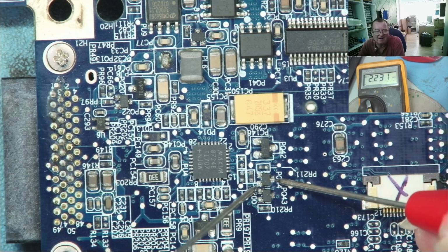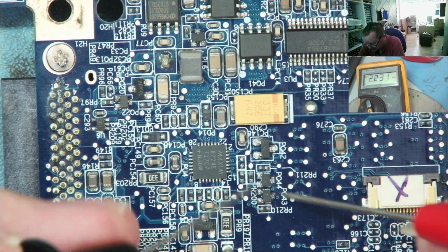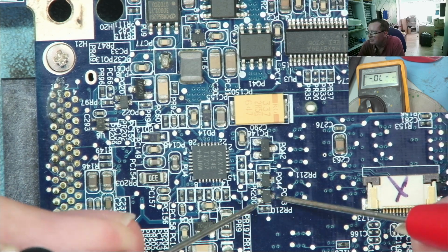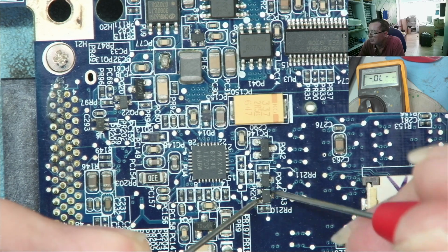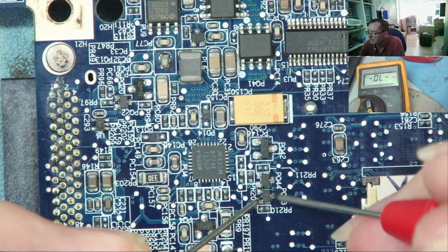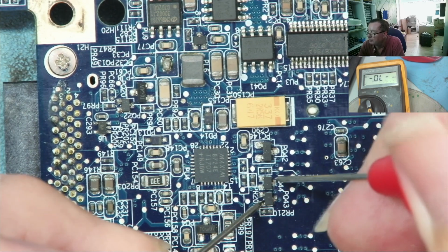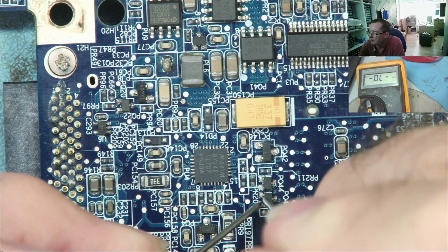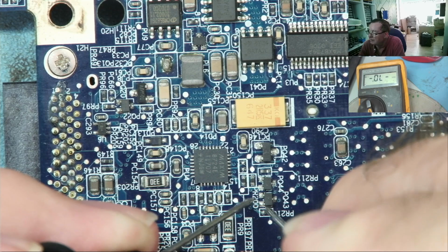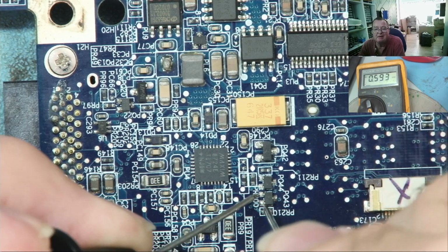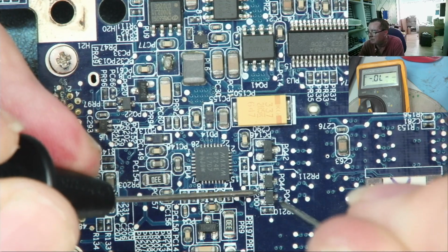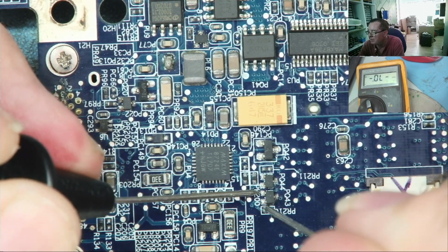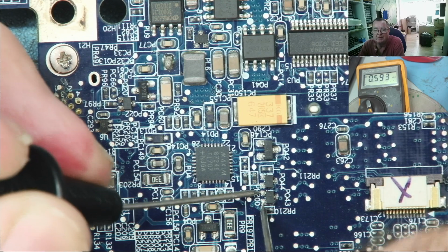Don't worry about the high readings I'm seeing here. Obviously, that's the sort of stuff in circuit. Does this one read the same? Go into the pin. Open. Nothing there. Now that reads like a junction with a black lead to here. Does this read the same? No. Okay.